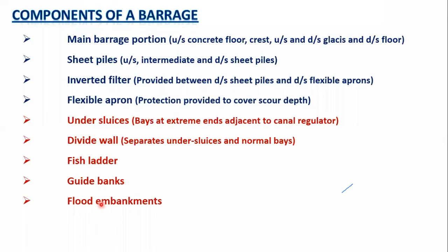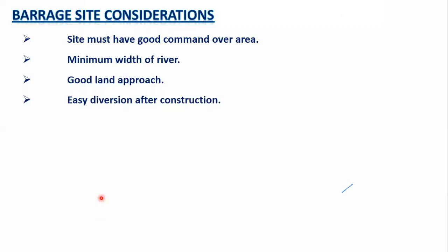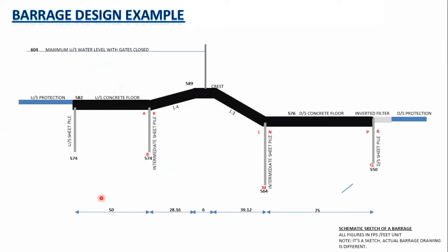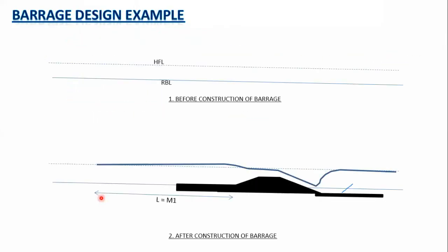Guide banks and flood embankments. For understanding guide banks and flood embankments, please see this upper sketch. Before construction of the barrage, the bottom solid line is showing the riverbed level and this dashed line is showing the highest flood level in the river. After construction of the barrage, the water will rise from the highest flood level or normal flow level. It will have certain upstream effects which are traveling